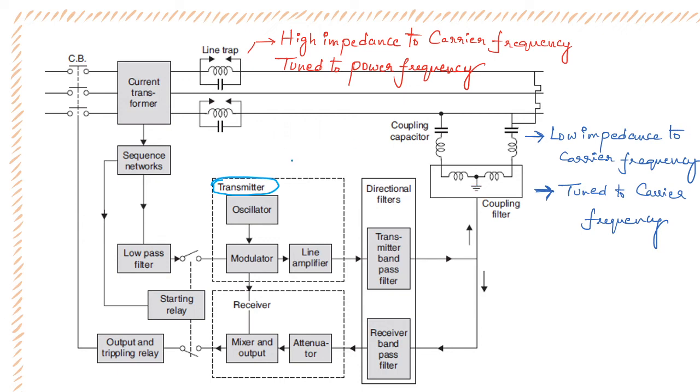See, we are using carrier signals just for protection, based on the relay schemes, and based upon the signals we are getting from the relays, we will communicate with the circuit breakers and other protection schemes. So to communicate that, we need a control wire from the substation to the location of the relays, or other substations or somewhere like that. Now we are sending the signals from these relay points, and basically I want to send that signal to the relay point over here, the circuit breaker operating point. I will call that the tripping point.